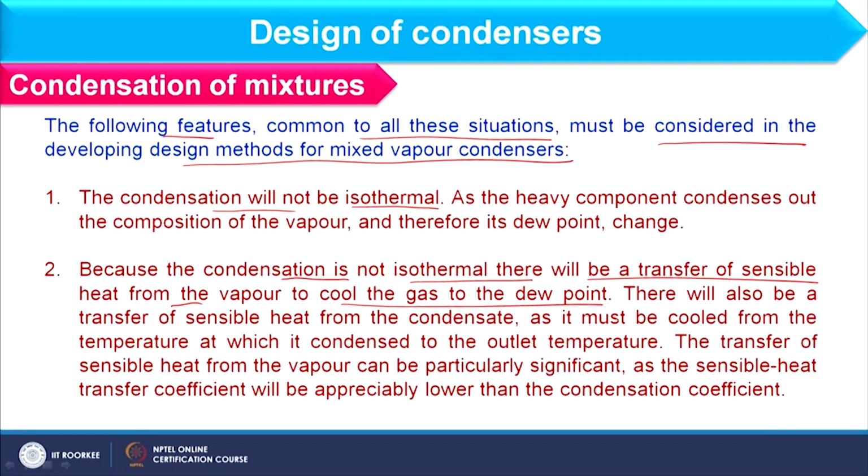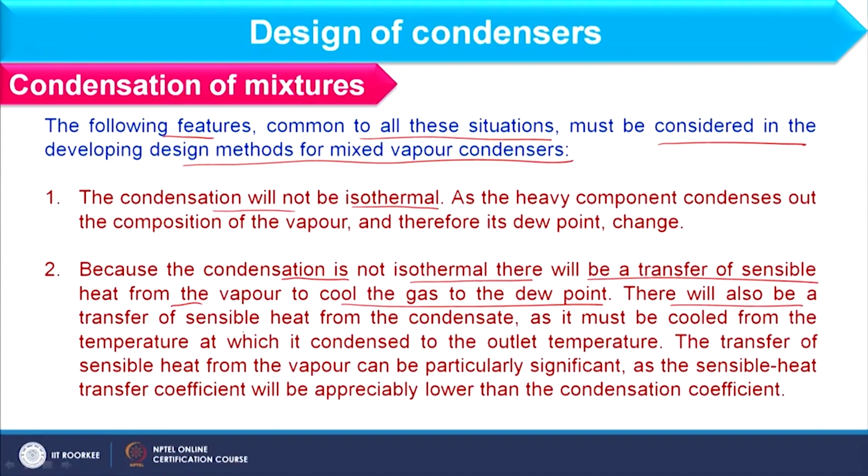So, instead of only latent heat transfer, we can have transfer of sensible heat also from the vapor to the gases. There will also be a transfer of sensible heat from the condensate, as it must be cooled from the temperature at which it condensed to the outlet temperature.